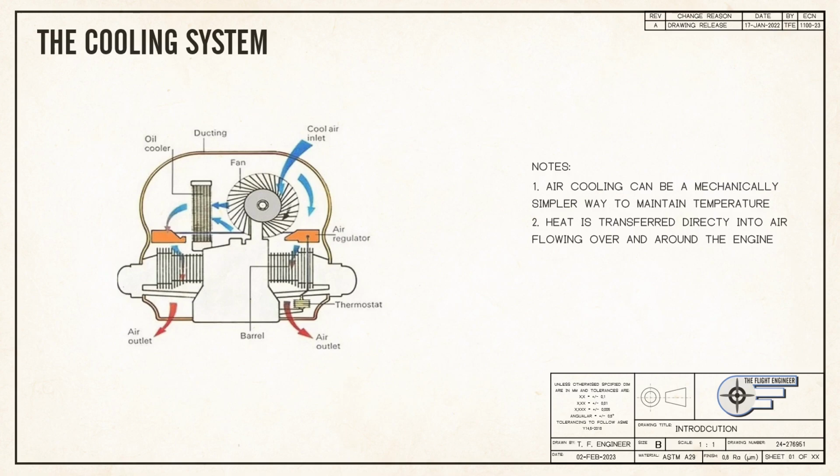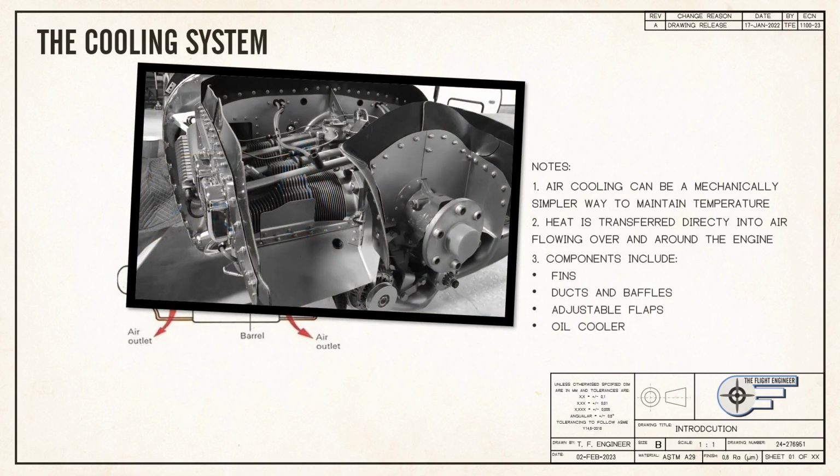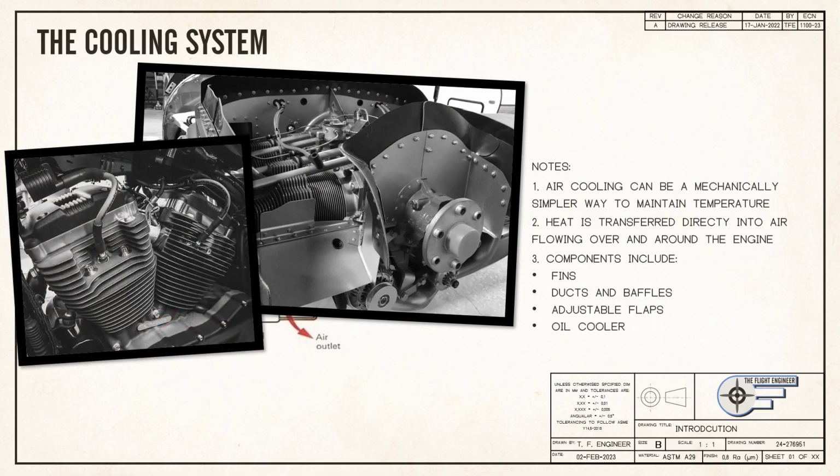Understandably, any application that utilizes this cooling system must encounter or produce a high volume stream of cooling air or risk overheating the engine. Components of an air-cooled engine will have cooling fins cast into their cylinders and cylinder heads. This increases the amount of surface area over which heat transfer can occur to the air. Large amounts of surface area are required, as air is far less thermally conductive than any liquid coolant.